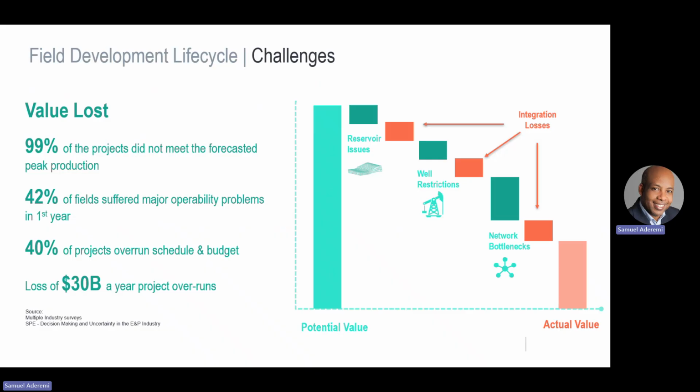One thing that we need to bear in mind is a well does not operate in isolation. Production from one reservoir can directly impact the performance of wells in another reservoir when they share the same gathering system or the same facilities. And this is where integrated reservoir and network modeling becomes important. By simultaneously considering the reservoirs, the wells, and the surface networks, looking at the whole system holistically, it will help us really understand the true potential of the asset and make better field decisions.